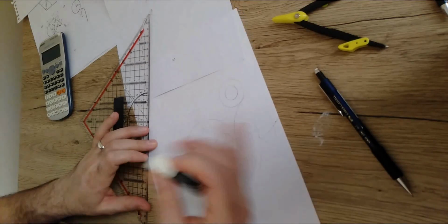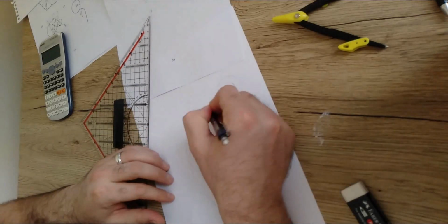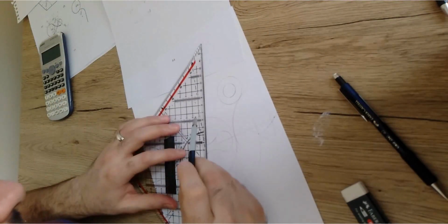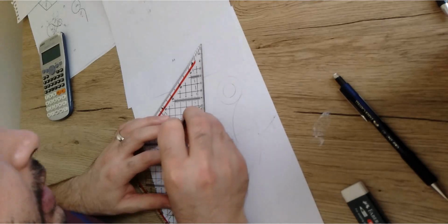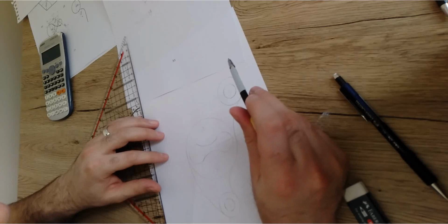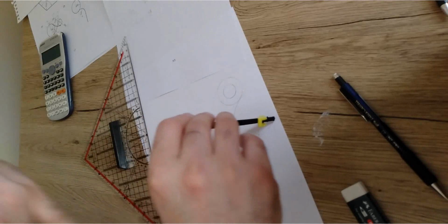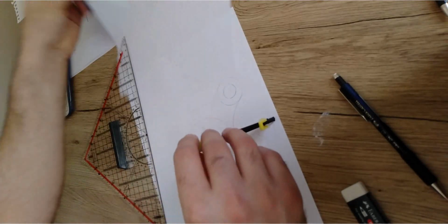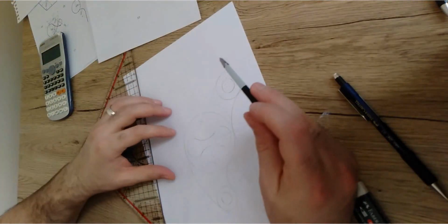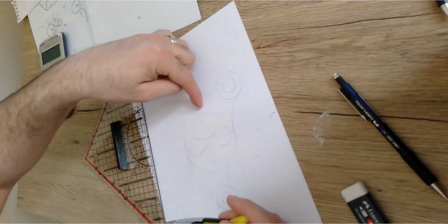I've messed up something here. Alright, it should be the center point of this curve R88 that I'm going to draw here. Then you're going to open the compass to 88. From this point, 88. Then simply you're just going to draw a curve. This curve should be tangent from here, but it has no other tangent. I have no clue where it's going to be tangent. It will be tangent to the R16, but we haven't drawn R16 yet, right? So you just draw a small curve here. Then we have to draw the R16 after that.